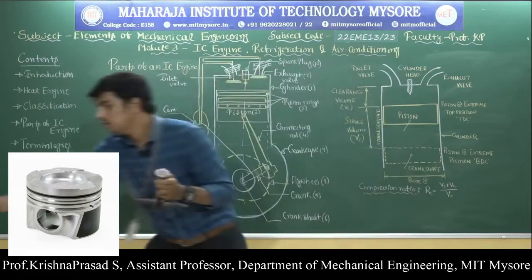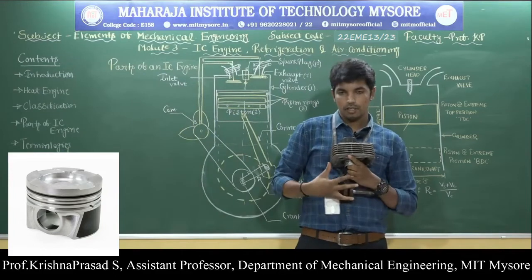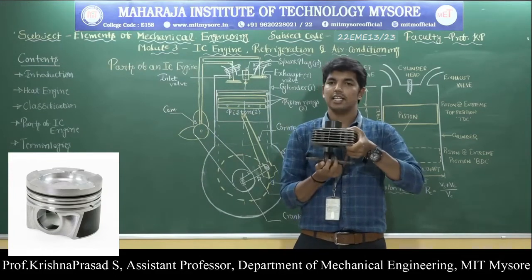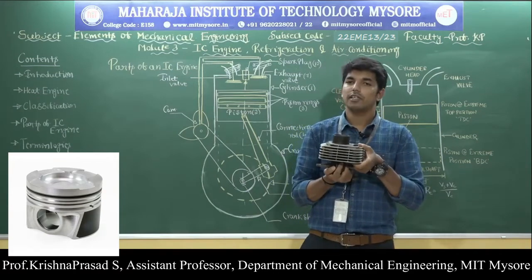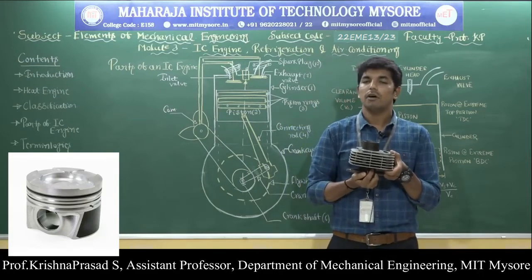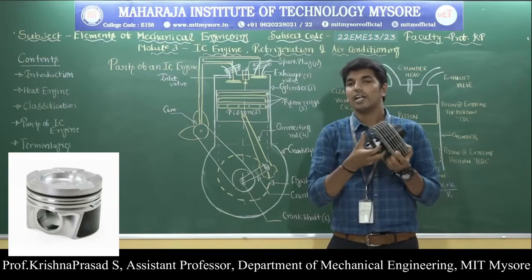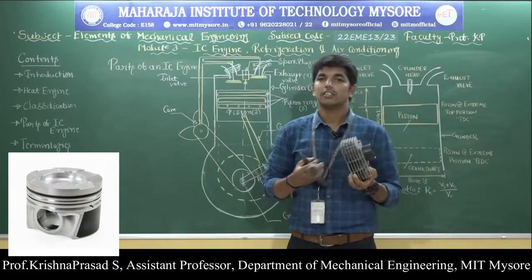So I repeat, what is meant by the piston? The piston reciprocates inside the engine cylinder. The piston is a cylindrical shaped component which perfectly fits inside the engine cylinder, and it compresses the charge, and the power developed by the combustion of the fuel is going to transfer from the piston to the crankshaft with the help of the crank and the connecting rod. So this is regarding the piston.